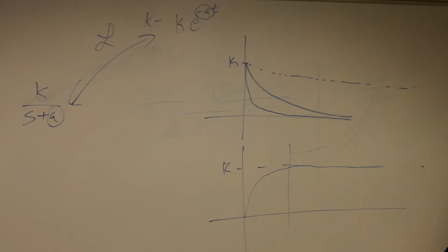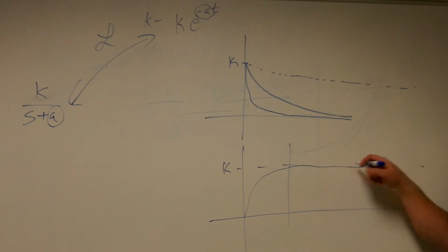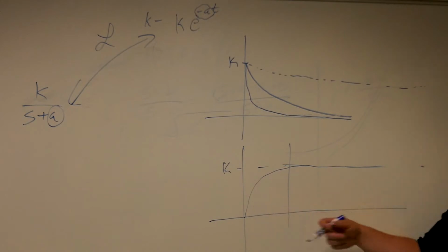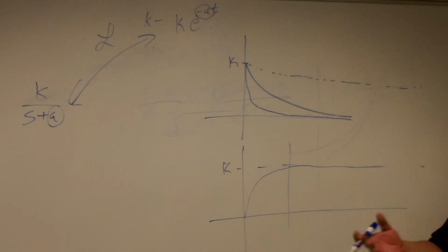Usually we say 4% or 2% or 1% or whatever amount of noise we'll allow on this signal to where the response is damped off that we can't tell the difference between it and noise. And so the period of time it takes to reach that is what we call the settling time.